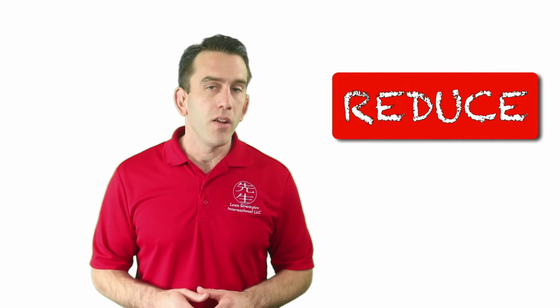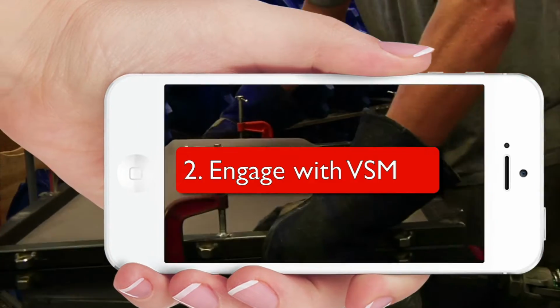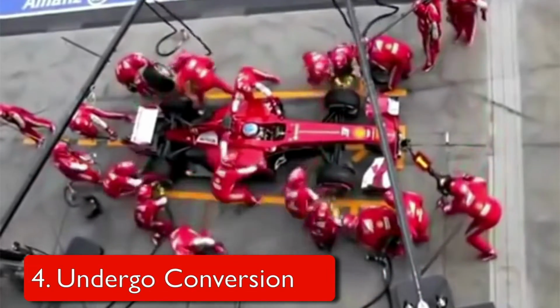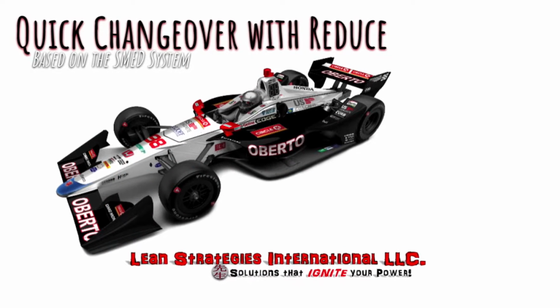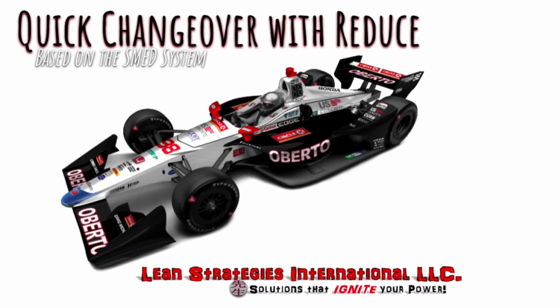The Reduce methodology is a more detailed method of performing quick changeover or SMED improvements. The steps in the Reduce methodology are required data, engage with value stream, differentiate internal and external steps, undergo conversion, clean up the process, and finally, ensure the steps work. As you can see, both the SMED and Reduce methodology have a very structured approach to them. In this course, we will focus on the more detailed Reduce methodology. However, we will revisit various aspects of SMED throughout the course. Let's move on to the next module.